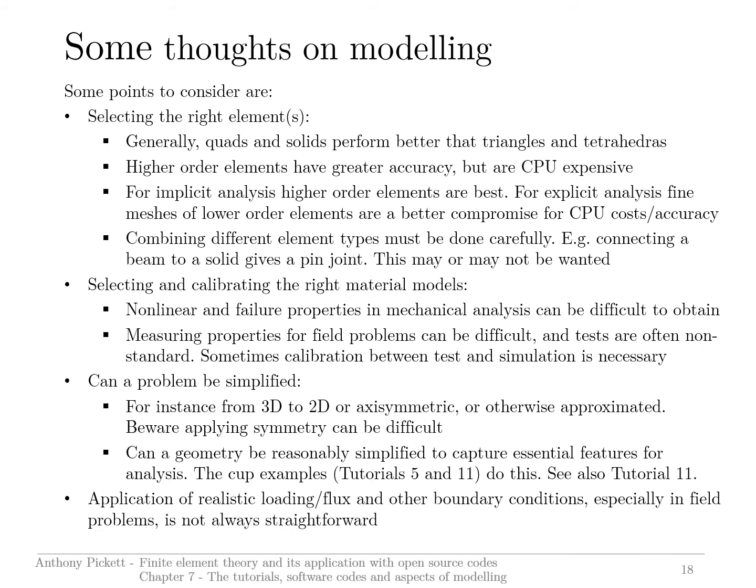Be aware, if you are joining different element types in a complicated structure, do beware the degrees of freedom that each element type has. For example, if you connected a beam having 6 degrees of freedom to a solid element to try and make some kind of a representation, this is possible, it's not a problem at all, but notice that only the translations will be connected.